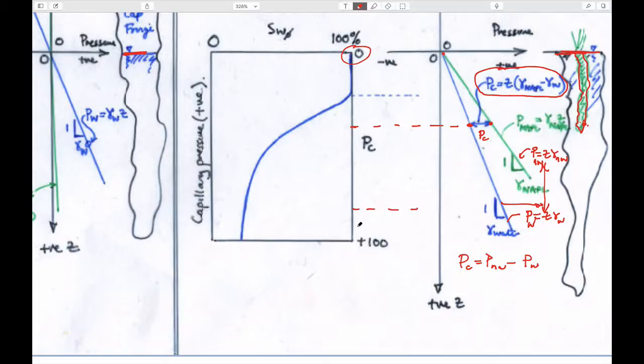And so what this picture tells you is that if you try and push this fluid in there, you actually can't get it in there unless you provide some kind of surcharge, say with a barrel that puts it in there and actually physically moves this line over, because it's got to get to this point before it breaks in at some non-zero saturation.